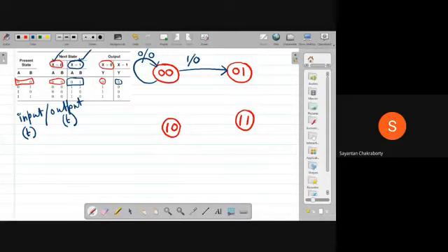Right? Now what happens? See, at any state 0, 0, 0, 1, 1, 0, 1, 1, there will be only two possible cases of input, 0 or 1. So there will be exactly two arrows or directed lines emanating from each of such states, right? Indicating the state transition if that particular input is applied, with the corresponding output also represented followed by a slash, right? So now it has moved to state 0, 1.